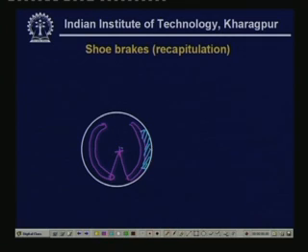So, there is friction material symmetrically placed again. These are internal radial shoes, and the force is applied here by some mechanism, and then these two calipers rotate about these two hinges, and then the friction material gets pressed and it develops the frictional torque.